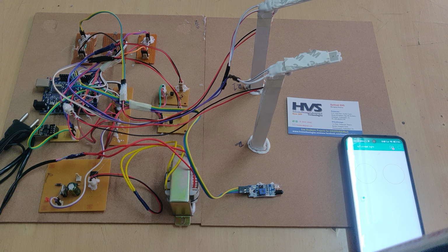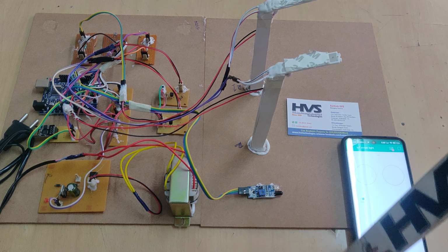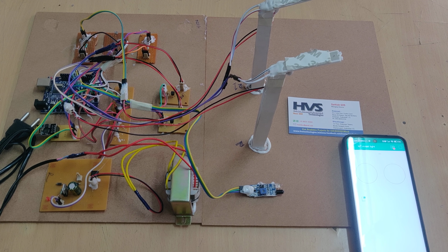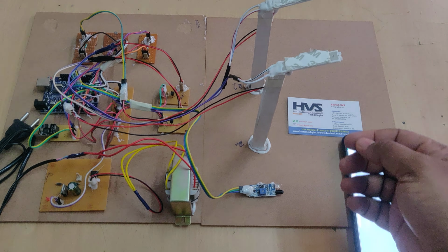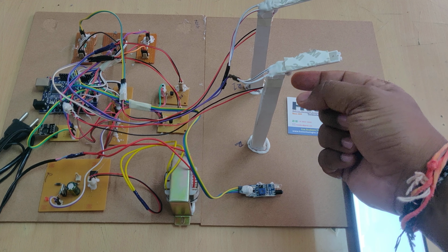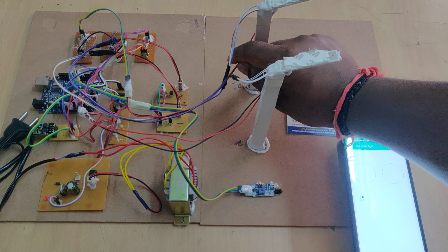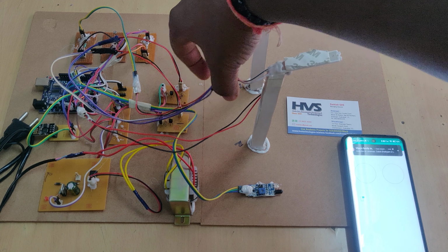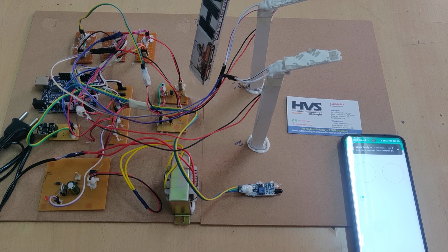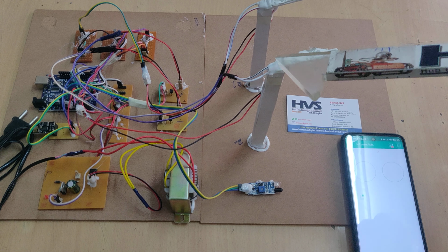To detect the day and night mode, we are making use of this LDR sensor. And next, to detect the vehicle presence, we are making use of this IR sensor. And next, fault detection will be identified by the LDRs which are attached to the individual street lights here. This is the LDR connection for street light 2, and this is the LDR connection for street light 1. These two street lights' power supplies get the signal from these two transistor boards. Here we are using transistors to control the intensity of these two LEDs.